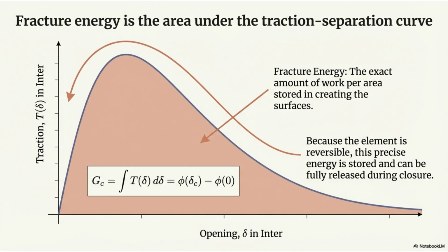Fracture energy is the area under the traction separation curve. This is the work per area stored in creating the surfaces. Because the element is reversible, this energy is stored and can be fully released during closure.